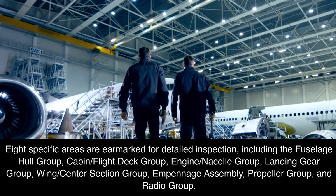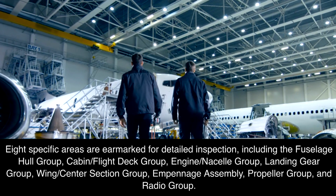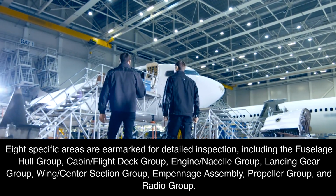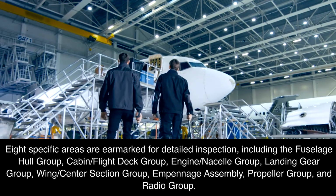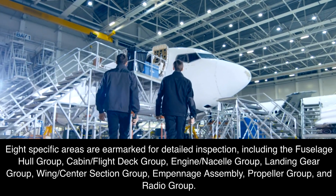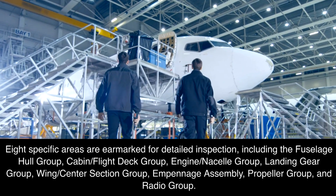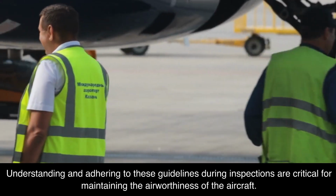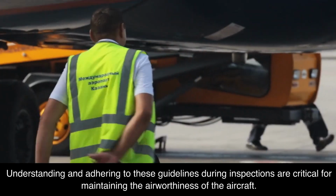8 specific areas are earmarked for detailed inspection, including the fuselage hull group, cabin, flight deck group, engine, nacelle group, landing gear group, wing, center section group, empennage assembly, propeller group, and radio group. Understanding and adhering to these guidelines during inspections are critical for maintaining the airworthiness of the aircraft.